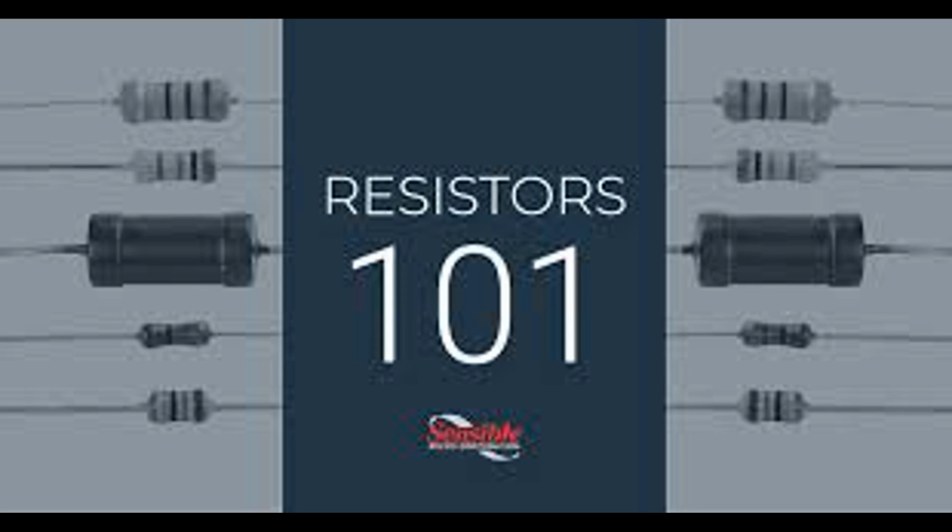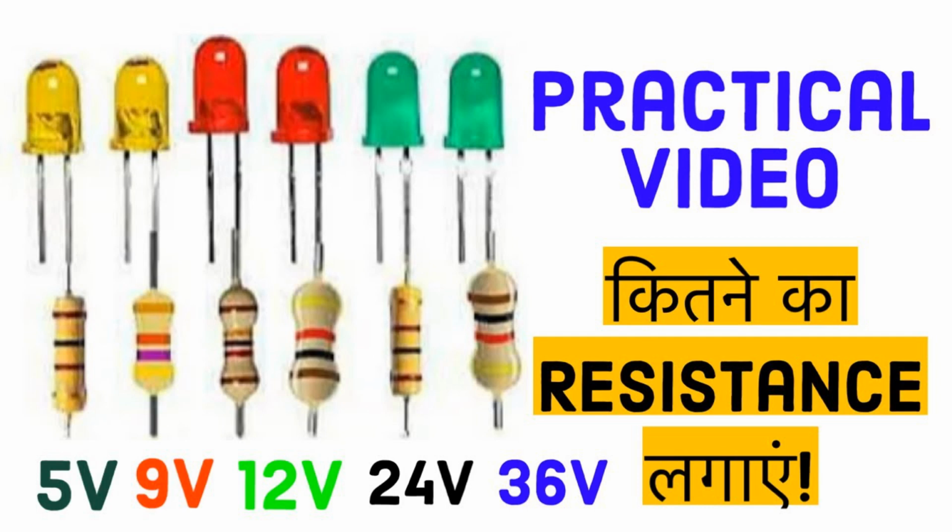Practical example of impedance matching. Example: matching an antenna to a transmitter. Problem: An RF transmitter has an output impedance of 50 ohms, but the antenna has an impedance of 75 ohms. Solution: An LC matching network or a quarter-wave transformer can be designed to match the 50 ohm source to the 75 ohm load, ensuring maximum power transfer to the antenna and minimizing reflections.